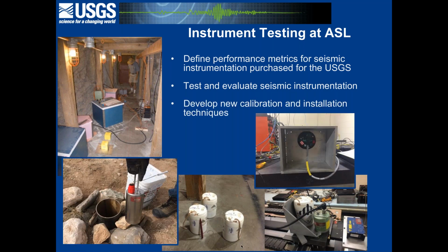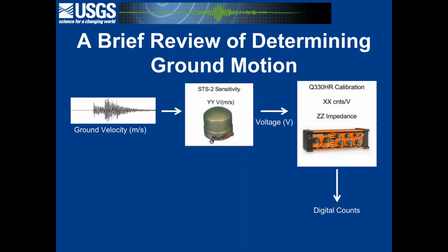We develop new calibration and installation techniques. Here's a post-hole sensor, which perhaps would have lower noise than a vault sensor in some of our ANSS field deployments. And here, this is showing a calibration technique to get the absolute sensitivity of seismic instruments.